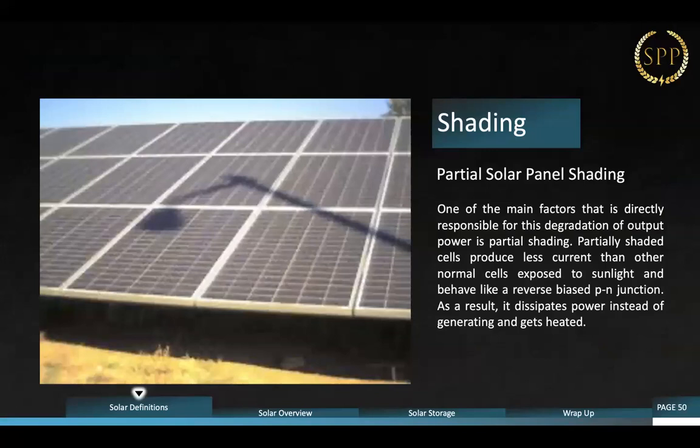So when we're building these things out, we're looking at the actual roof, like, hey, we have a roof pipe up here, and that's going to be about 3 feet, so it's going to cast this shadow year round. So we want to make sure we avoid that shadow. Now, there's a couple of our guys out in Waco, Texas, where if we cut back our trees or take them down, we lose property value. They have huge trees that literally cover the entire roof. That's a problem for solar because there's nothing much we can really do there without cutting down those trees, because the panels are going to be shaded throughout the entire year.